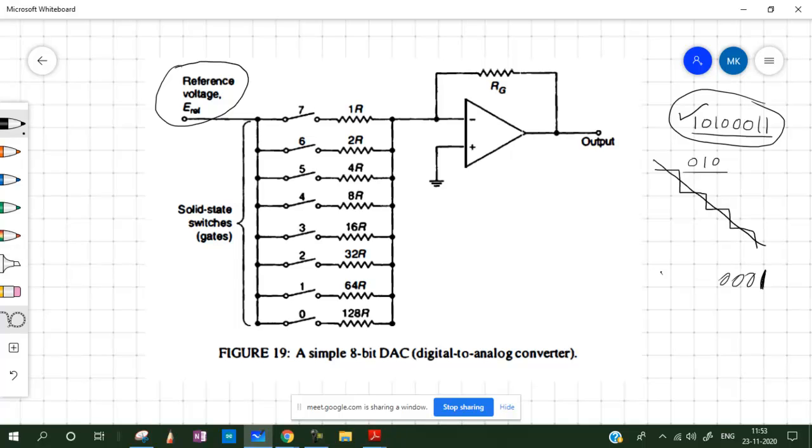So 1 2 3 4 5 6 7 8. All right, so this would mean just one, isn't it, the least significant bit. So this means obviously a very low voltage output, or current output, isn't it? So what happens is, because of this one, this gets connected. There is some reference voltage, for example 1 volt or whatever we want to give in terms of digital signals. So this will be divided, because this will act as a voltage divider, isn't it?